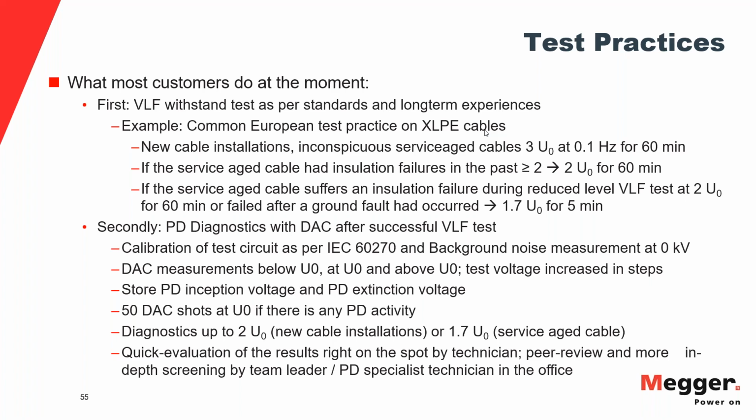After they pass the voltage test on new cables, they would do the diagnostic test with the damped AC. The latest new trend is that you combine the two, the voltage test and the PD test, into a monitored withstand, but then you need a continuous waveform for that. So then it would be sine and not damped AC.